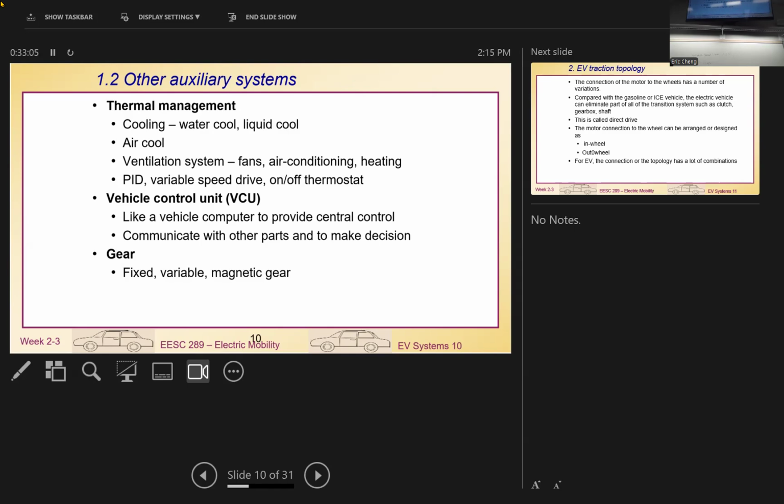And also for their motor, they use an inverter. One key thing, if you use a motor drive here, the frequency applied to the motor is higher. I'm not quite sure if you've heard of the name pulse width modulation. Have you heard about this name? PWM. Yeah, PWM. PWM is the technique we use to output from an inverter to a motor.